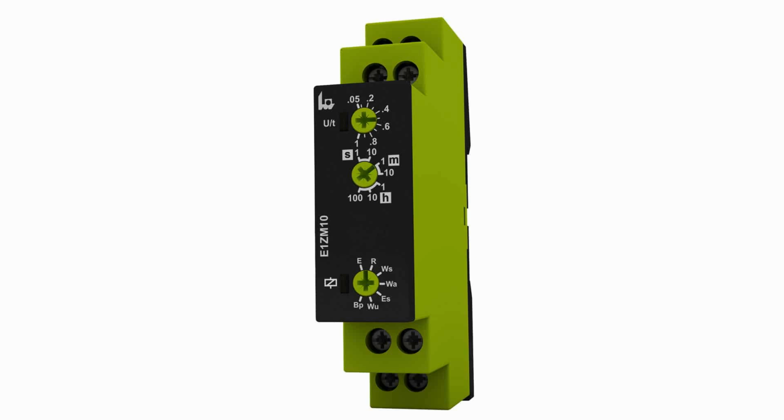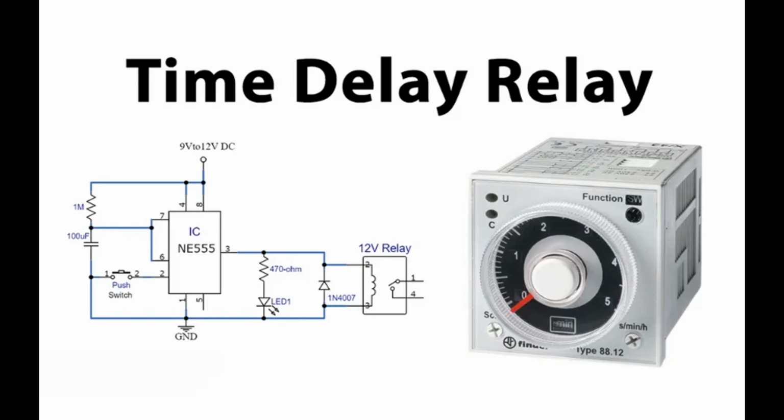Overvoltage protection. Overvoltage protection safeguards the relay and circuitry from voltage surges or spikes above the rated voltage, which can occur due to lightning strikes, power grid fluctuations, or switching events. Overvoltage protection devices, such as voltage clamping diodes or transient voltage suppressors, TVS, limit the voltage to a safe level, and prevent damage to sensitive components.